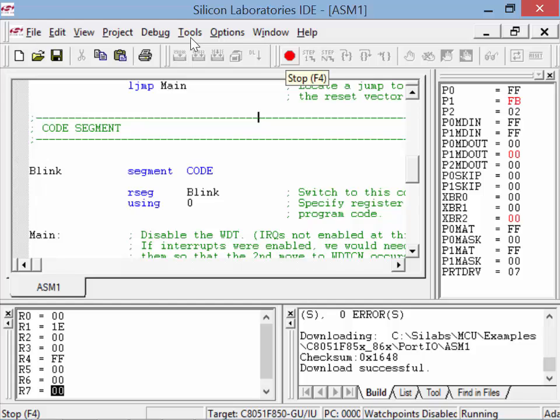And now you can see that I've got them flashing opposite of each other right there. So yeah, the set command doesn't work with this particular assembler for some reason. But you can see how we can look at the hardware and we can write the code for this particular processor. I know with the 8086 you didn't do any of this.